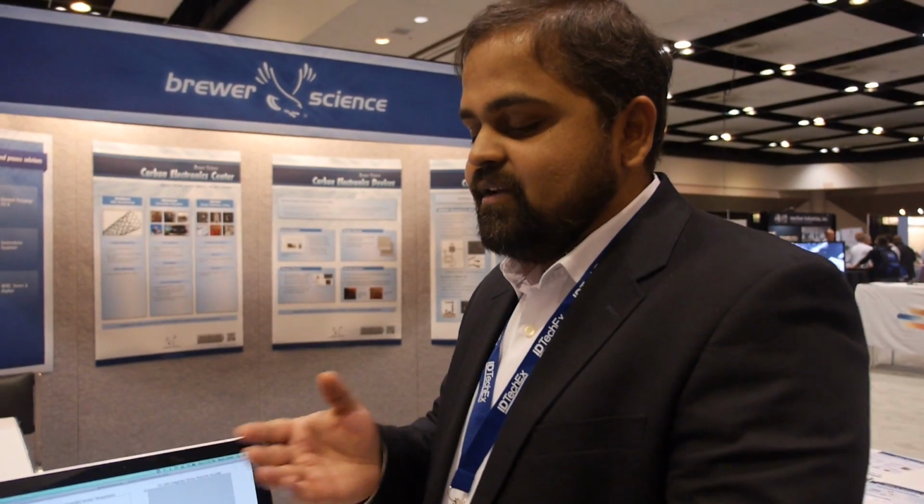Temperature and humidity sensor on its own is an environmental sensor, and it can work with other sensors to give compensation, because sensors traditionally drift with temperature and humidity, and this gives compensation signals. Do different people have different levels of humidity? Yes, it senses humidity between 20% and 80%. That's the standard, but it can extend to the full relative humidity, and it can also measure absolute humidity because it's integrated with the temperature sensor.